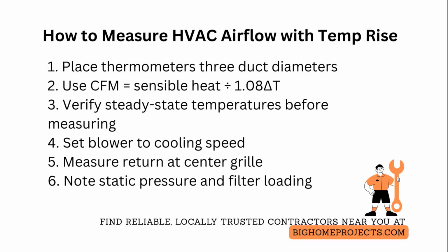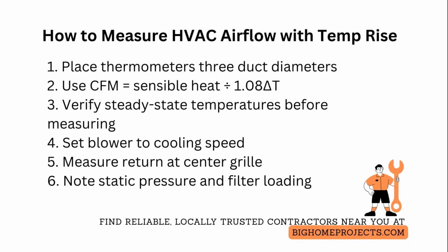For best accuracy, cross-check temperature rise derived CFM with a flow hood or traverse measurements at least once per year to validate your method and calibrate offsets.